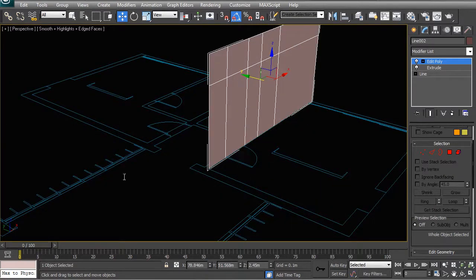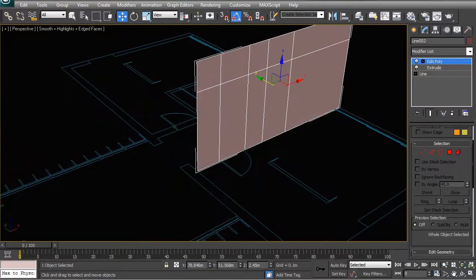What I first want to do is set up all my walls, and I'm going to worry about the heights later, since turning your sections and elevations on and off is going to be quite time consuming. So you can do that all later unless you know the exact heights already. What I also like to do at this stage is have my AutoCAD open at the same time and just go across to AutoCAD and measure off your distances and heights over there, and then just carry across those heights into 3D Max. It is a lot quicker to do that than actually turning on your elevations in 3D Max itself.